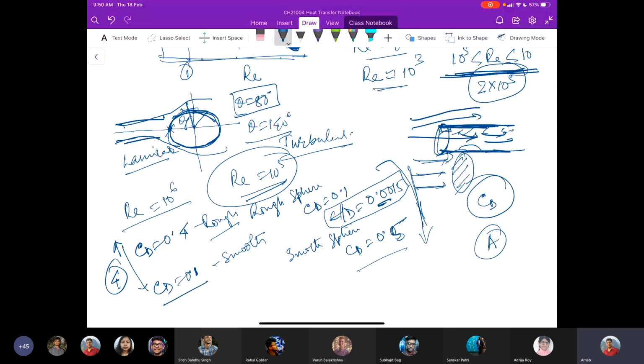So that area for a cylinder, remember the cylinder is placed like the long surface here, over which the flow is happening. So A on which the drag force is acting is basically the length L and the projected characteristic length, which is the diameter of this body.